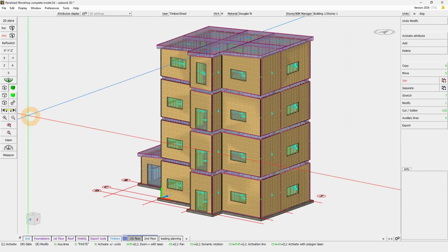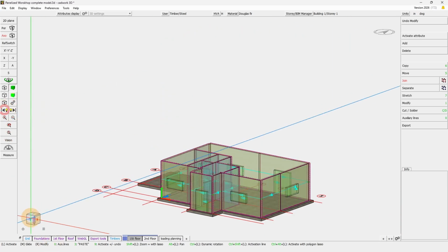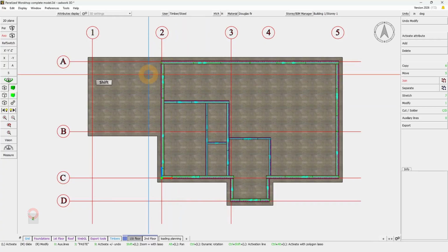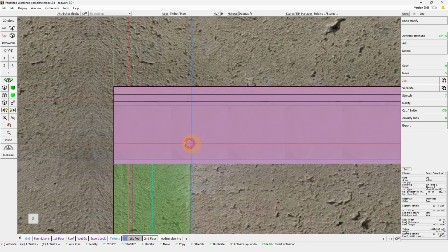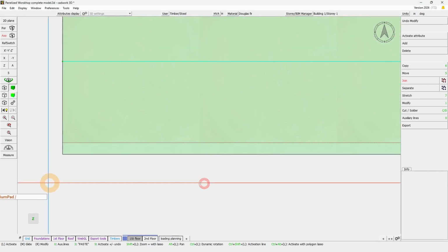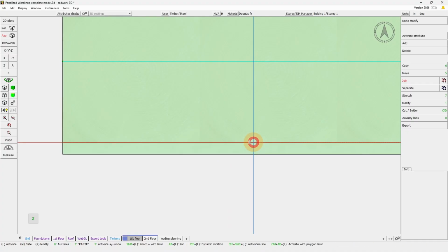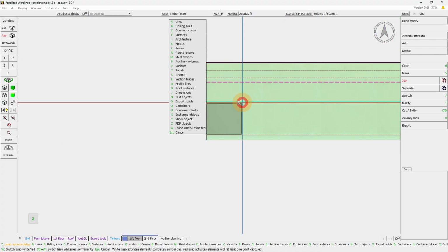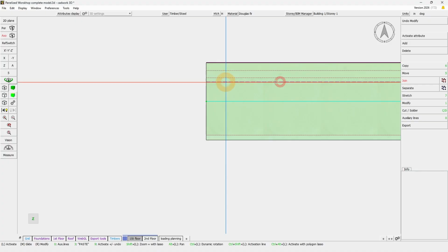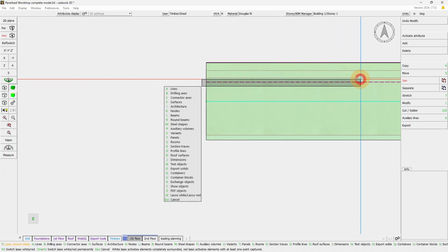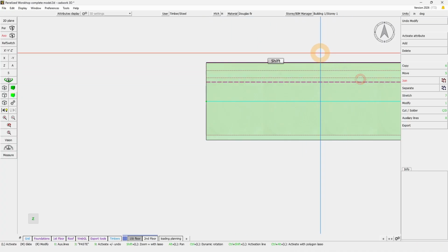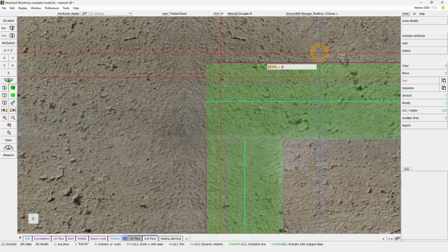If we focus here only on the walls of the first floor, we'll see that this wall actually allows you to display each layer. If we only look at one here, we can easily see that there is some sheathing inside, then a structural frame, followed by sheathing, batten, and then finally cladding. One thing to note is this dashed line here. We are going to look into what this is in more detail afterwards.